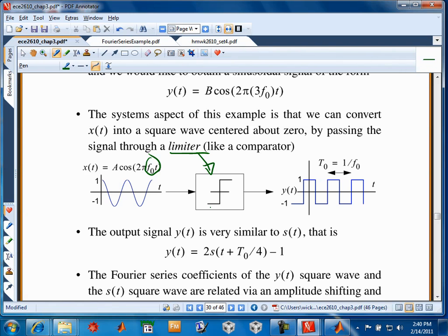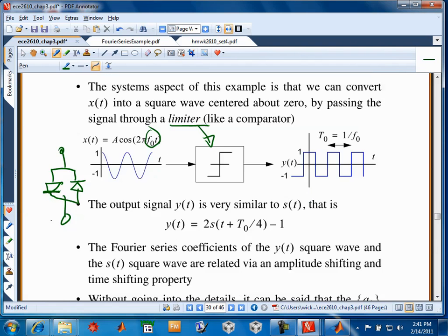And on the circuit I'm passing around, there are two black devices soldered back-to-back, and those are diodes. They're actually a high-frequency diode called a Schottky barrier diode. So I'm putting a little diode circuit across there, that looks like this. Those diodes conduct in one direction and not the other, and when they conduct, they clamp the signal to a certain voltage drop. So those diodes can convert the sine wave to a square wave, and I'll show that in the demo on Friday.